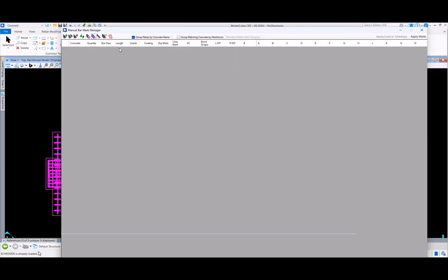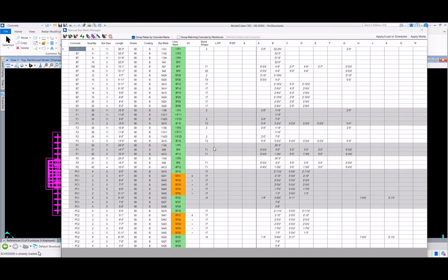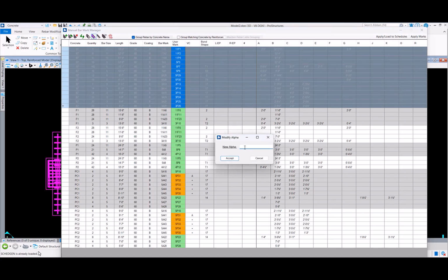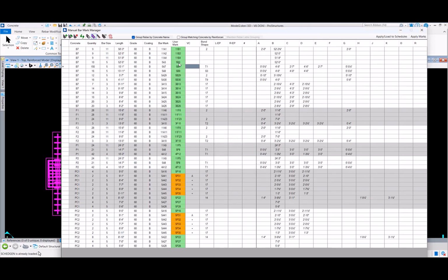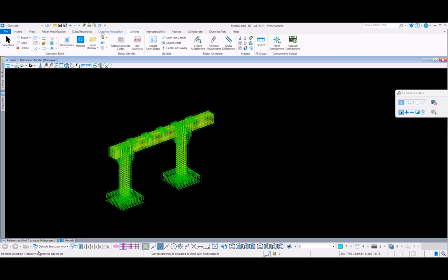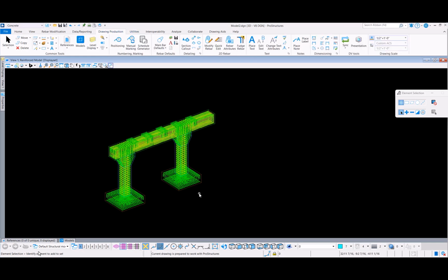So as the bars have ID now, and we selected them, now it's being grouped, and this is the bill of materials. So before we used to do these rebar quantities all by hand, now it's fully automatic. And any changes in the model will trigger changes on the bar, and then we just need to rerun the quantities, being able to generate this fully automatic, even manipulate it if we need it after the fact, group it different ways, so accommodating to any design standard that we may want.